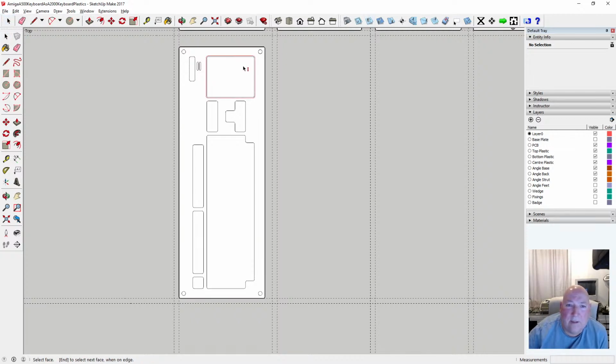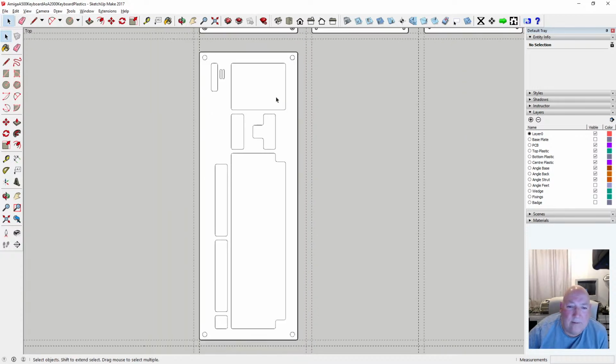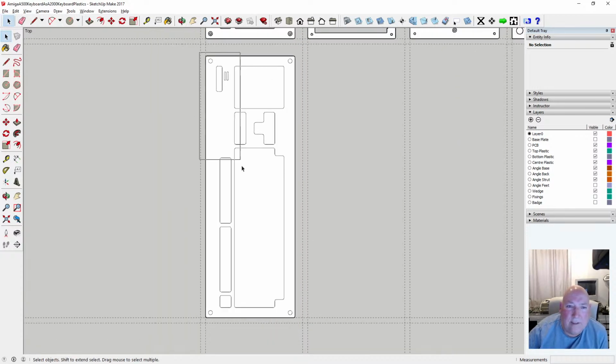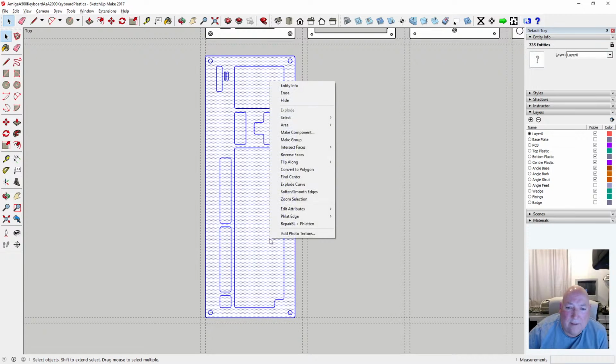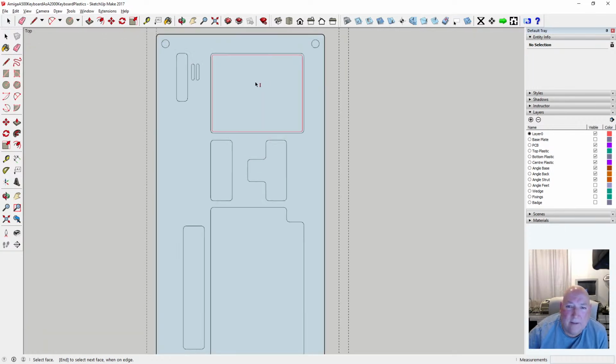Yeah, that's when you do an outside cut, even though I'm on the inside cut tool. So probably what it needs to do is to really select all this lot, reverse the faces. Let's try that now. Let's try and do an inside cut. Yeah, let you do an inside cut now. See the red lines on the inside, because that's the toolpath for the milling bit. If you're on the outside, your milling bit's got to cut the wrong size.